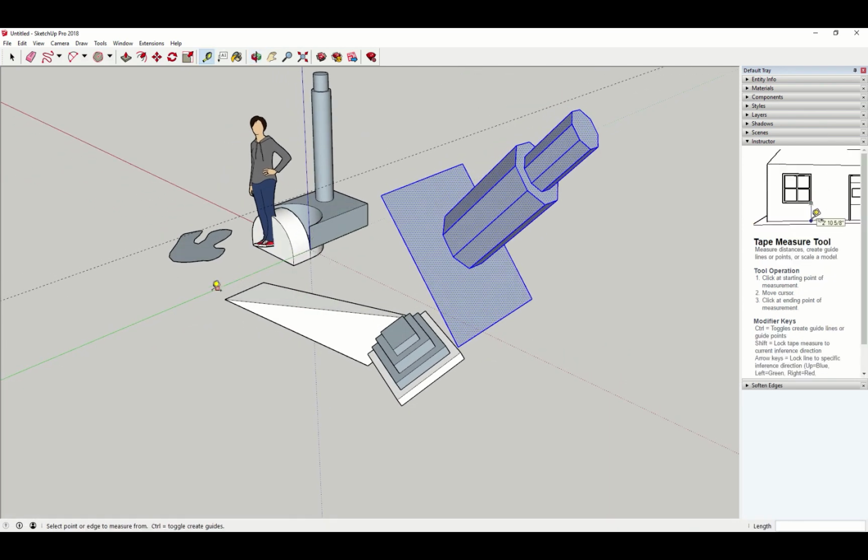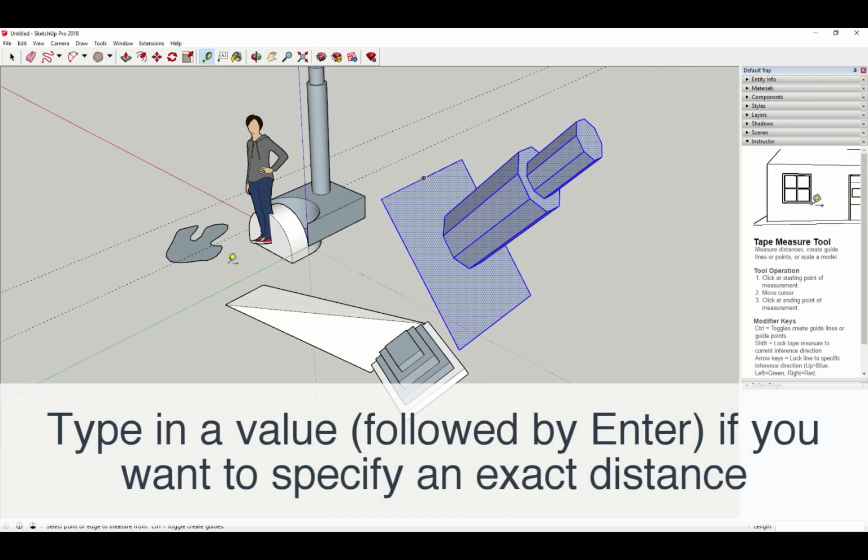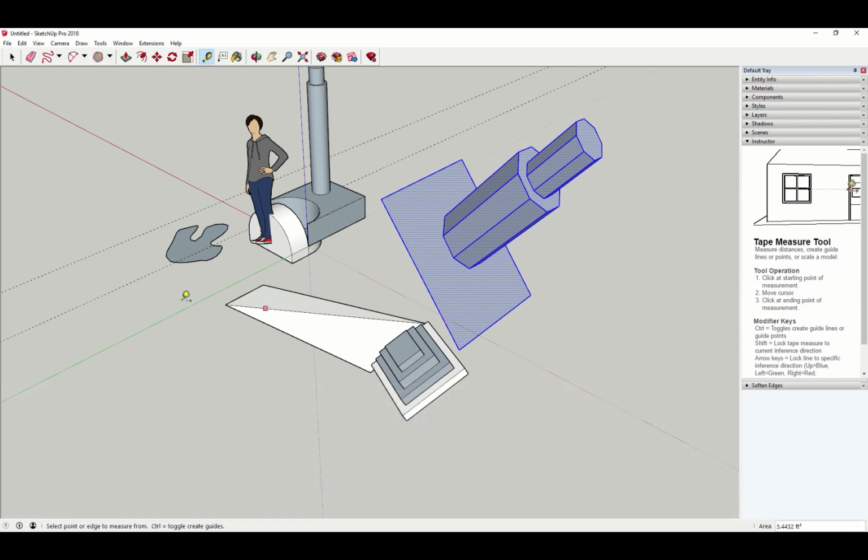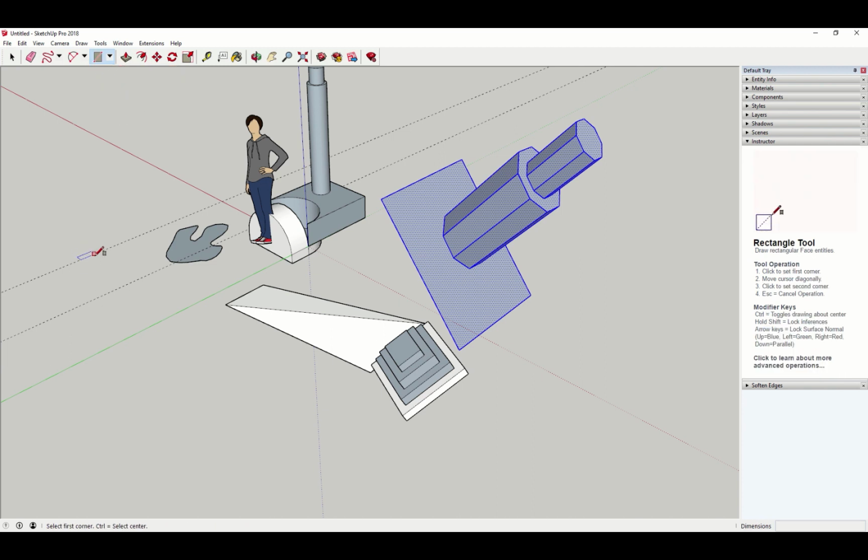Okay, and people use these reference lines quite a lot when they're laying out a space. For example, here, let me undo that, and I'll make a reference line that is, oh, I don't know, 3 feet from the plan. Then maybe I make another reference line that's another 3 feet. See how I'm using my value control box. You can set up a little grid for yourself, which will allow you to snap to it. So when you're drawing, say, here, let's draw a rectangle. You can snap to that grid, okay? Very handy. So those are the basic drawing tools. The text tool is a funny one because we are in a 3D environment.